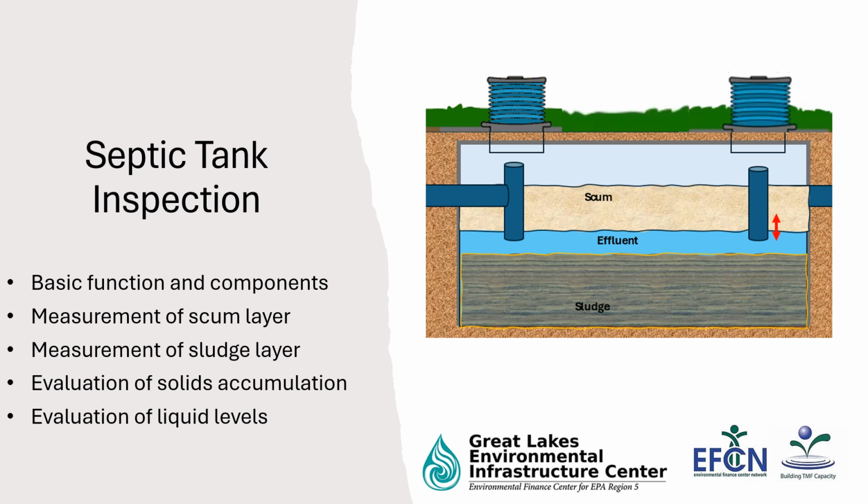Welcome to today's video on septic tank inspection. We're going to begin by discussing the basic function and components of on-site wastewater systems. And we're going to delve a little deeper into the measurement of the scum and sludge layers in a septic tank in order to evaluate the solids accumulation. And lastly, we'll talk about evaluation of the liquid levels in a septic tank.